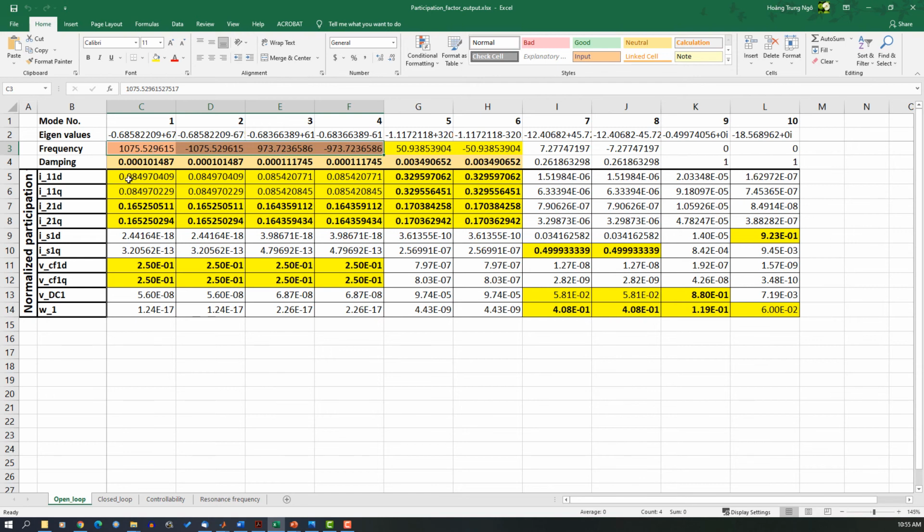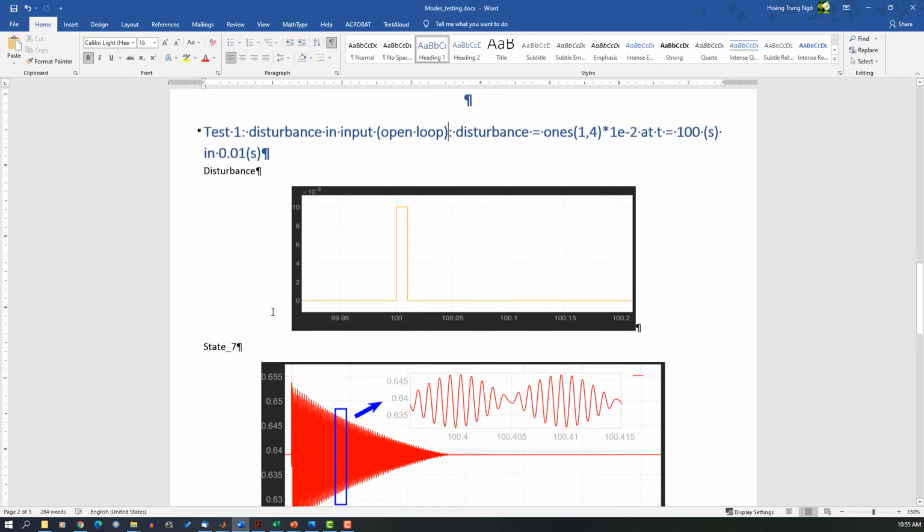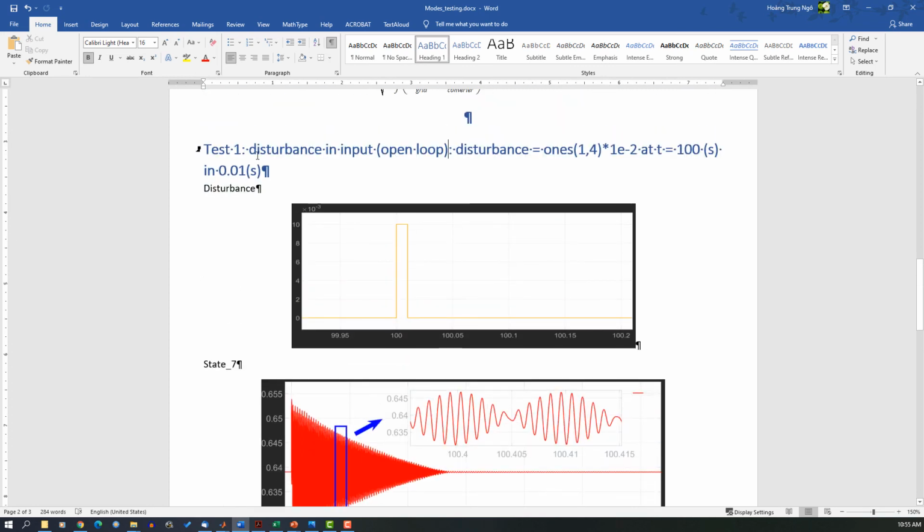So from this, how can you see this oscillation in your system? The easy thing is to inject a disturbance in the input. So at the operating point, you plot something like this. Here the operating point is 0, so the input could be 0 actually.